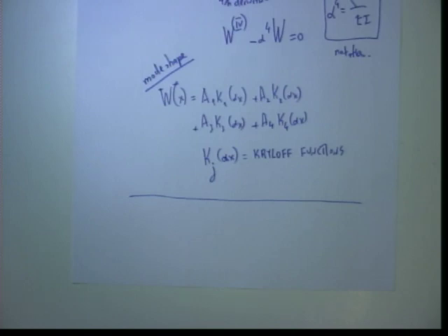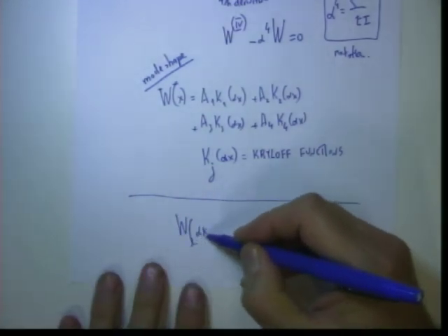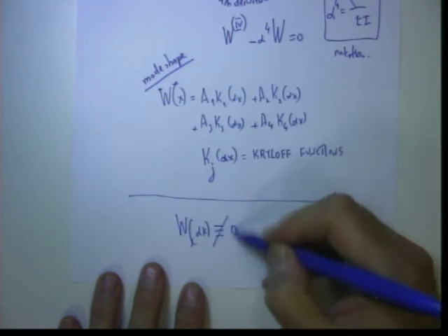Had it stayed straight, it would not be vibrating. It cannot stay straight because there are two points where displacements are zero. Had it stayed straight, displacement would be zero everywhere, but then we would not need all this analysis. We were looking for the solution where W(x) is not zero everywhere.